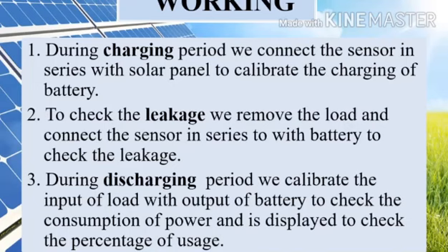And now I will discuss the working of our project. During charging, we connect the sensor in series with the panel, then it will show how much percent battery is charged on your mobile. And during discharging, we calculate the input of the load with the output of the battery. Then it calculates the consumption of the power. Then it will show how much percent battery is discharged on your mobile. And during leakage, we remove the load and then connect the sensor in series with the panel. Then it will show how much percent your battery is leaking.